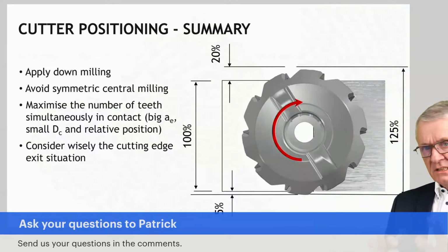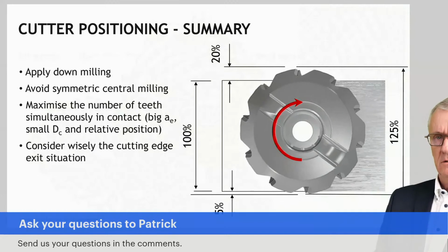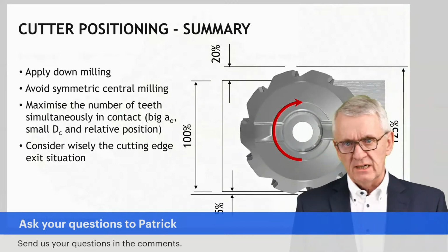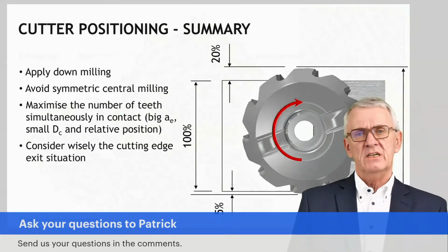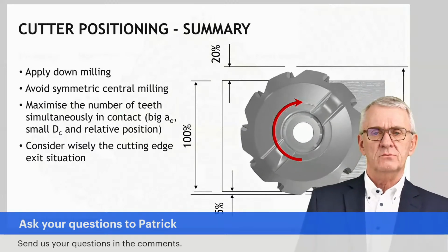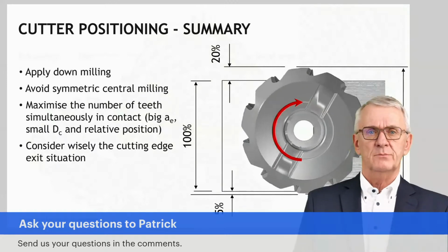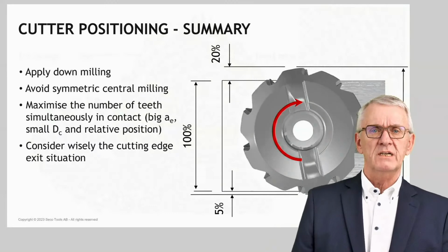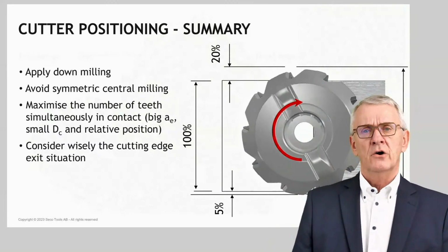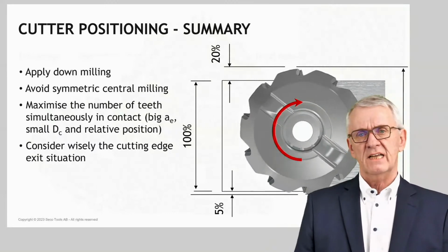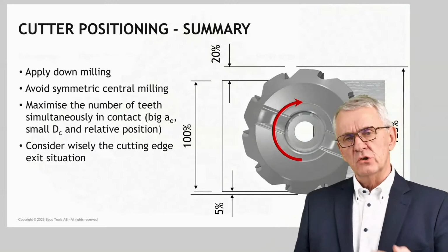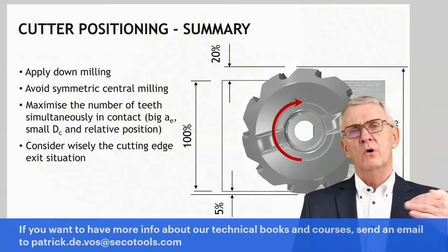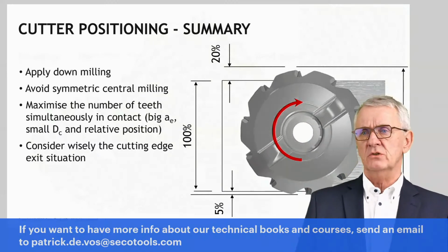And I know it's a bit theoretical. But next to theory comes the expertise you all have. In theory, we say the milling cutter should be 25% bigger than the radial depth of cut. The workpiece should not be positioned centrally in front of a milling cutter. There should be some overhang on entry and some overhang at exit. The overhang should not be symmetric. There should be less overhang on exit and more overhang on entry, and so on and so forth.